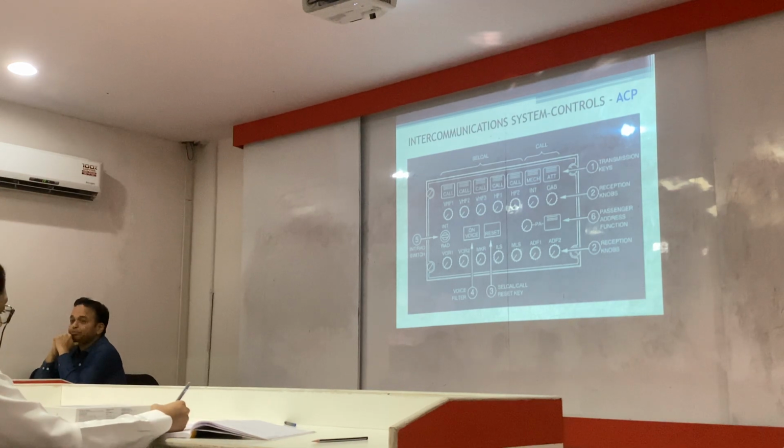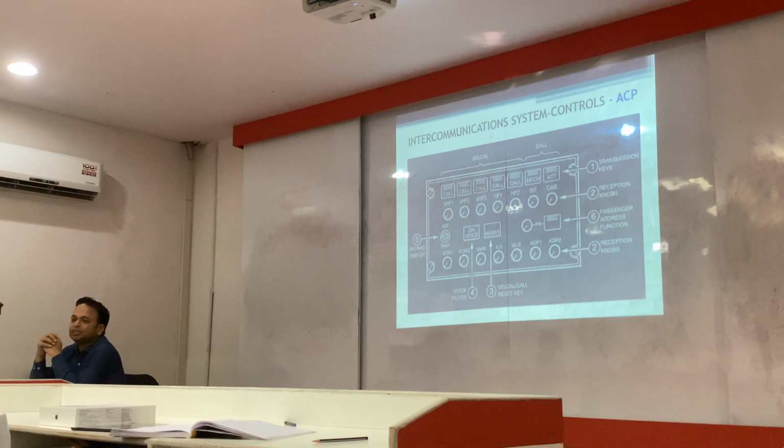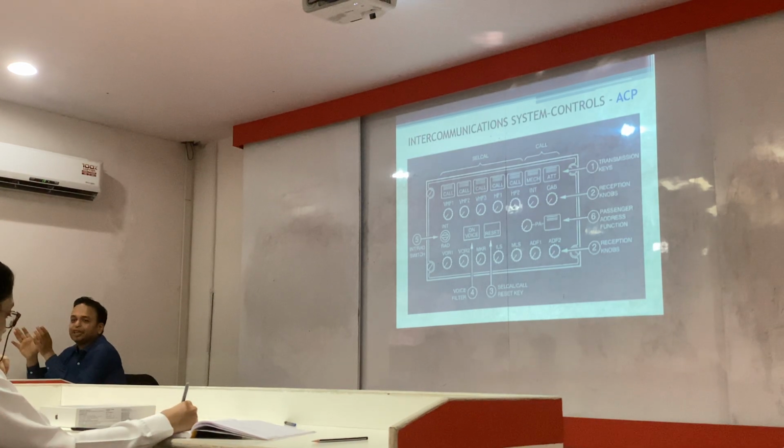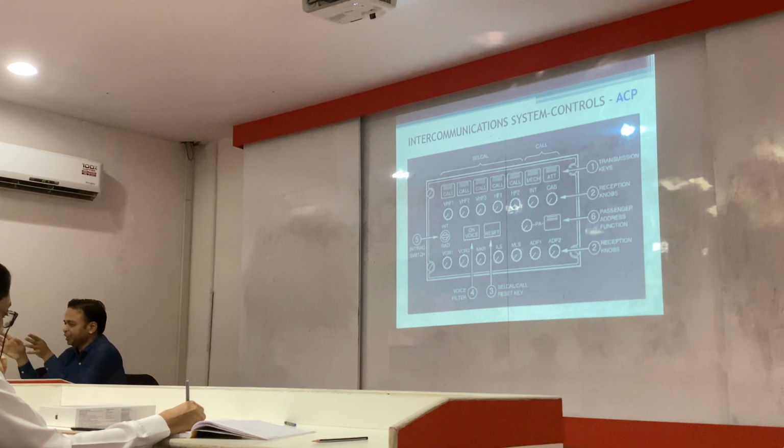PTT stuck. Basically, this is the cause. Or ironically, as per Airbus, this particular message shouldn't be coming. Instead of this, there is this new message which should be coming, single PTT stuck. Okay? So still you have got this message coming, and because of which our two aircraft have come back and landed straight, 321 aircraft.